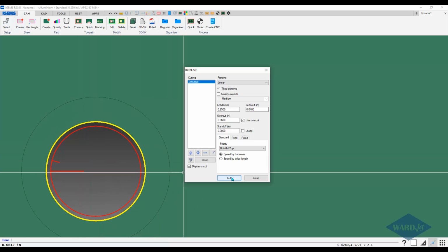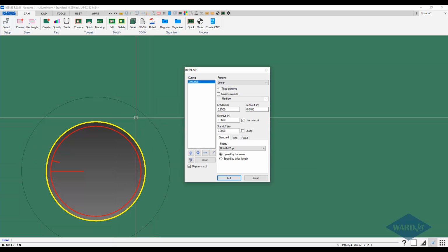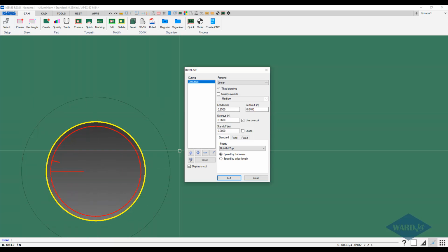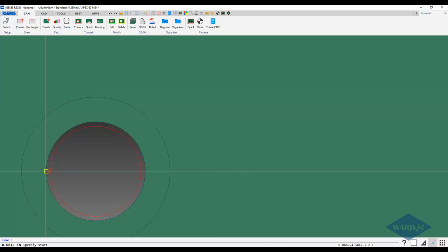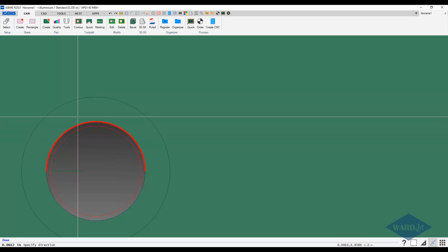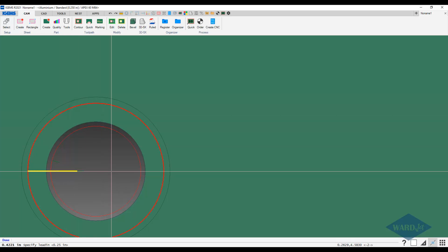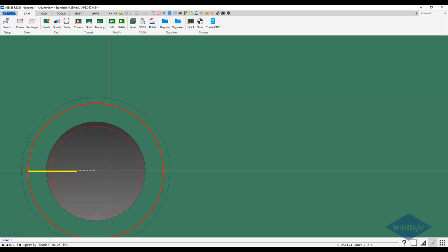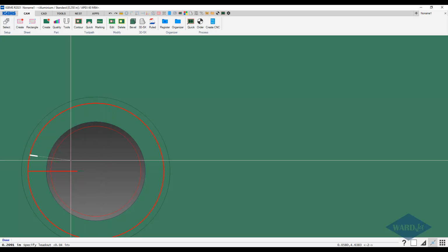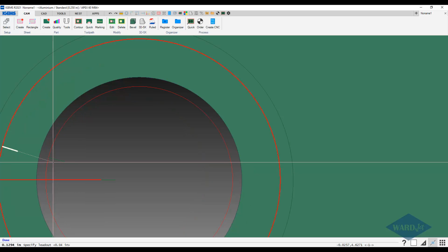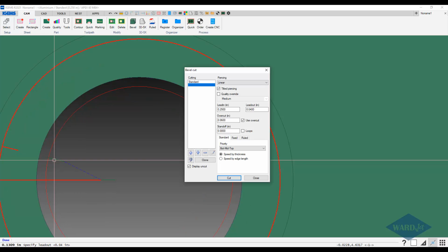And now for the countersink, we see the yellow line here indicating that there's another edge that needs toolpath added to it. So I can click on cut again, and we'll start at the same point, and I'll hit enter to go all the way around, and again we'll go clockwise. And then for my lead-in, when it locks in there, I'll take the default length and hit enter, and then same thing for the lead-out: when it locks in there, I'll hit enter.